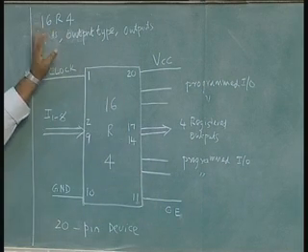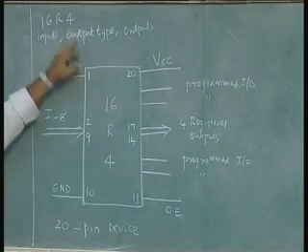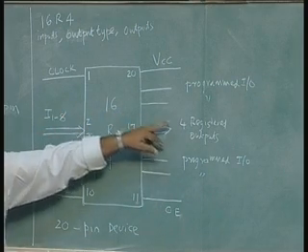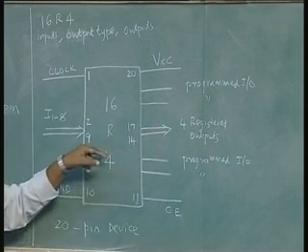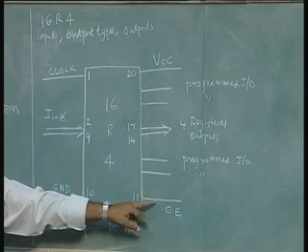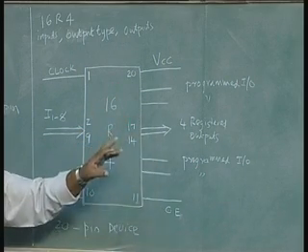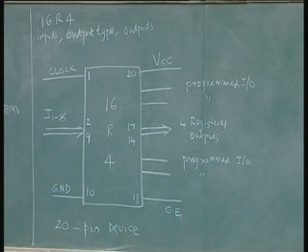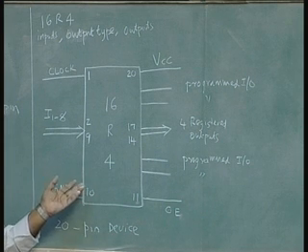So that is why he is not totally wrong, because R4 means 4 registered outputs. These 8, these 4 are, even though they are 4 registered outputs, all the 4 can be used as inputs also, plus another 4 inputs are possible using the output enable, which caters to all these 4. This is how we get 16R4. So this example shows how the device is sort of organized and very versatile.